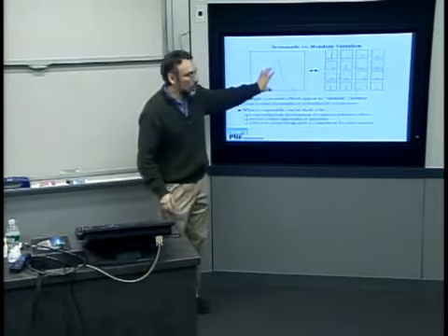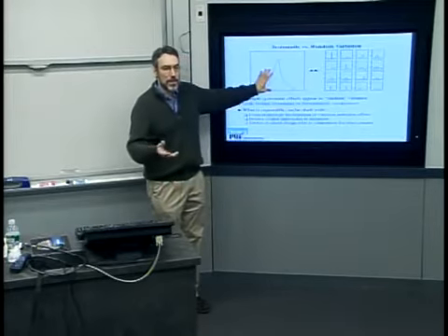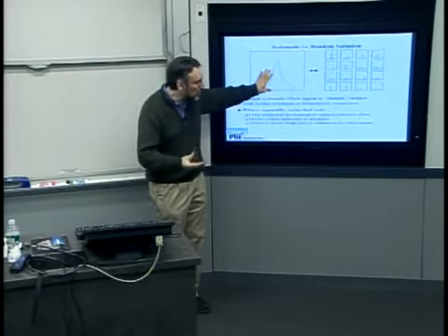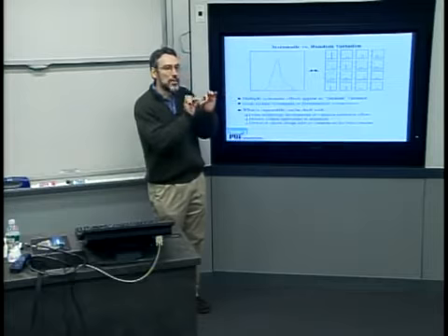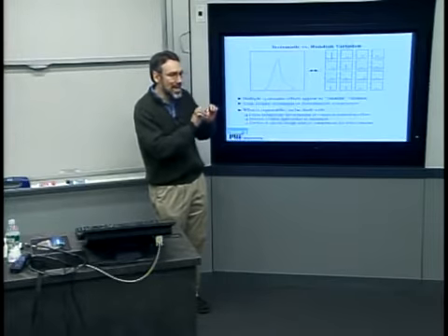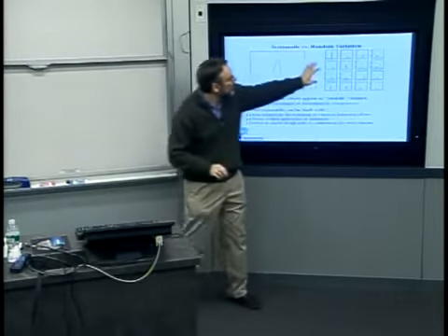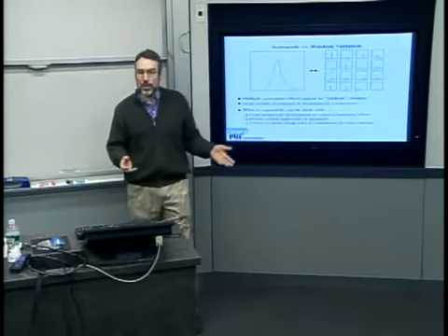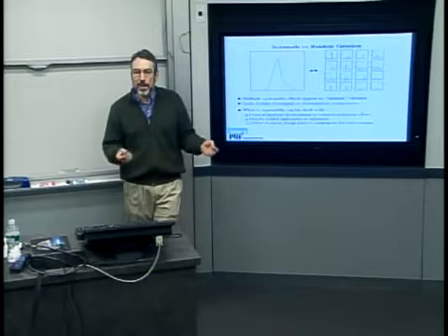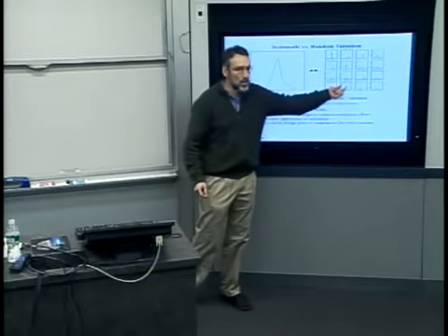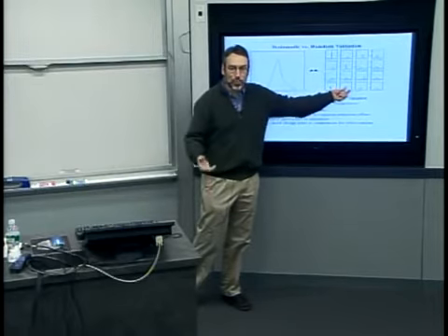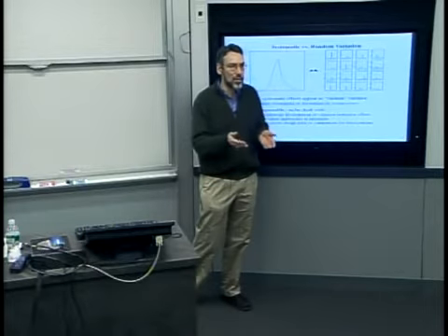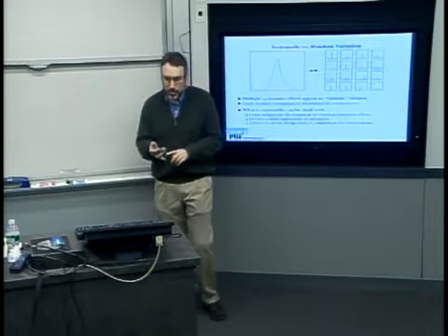And a lot of work will be done in designing test procedures, designing process control charts and whatnot to be able to track individual contributors and separate them out into the component sources of variation. Why do you want to do this? If you can identify individual sources, that's crucial to being able to go and squeeze them down, right? You got to know what the source is in order to remove it.